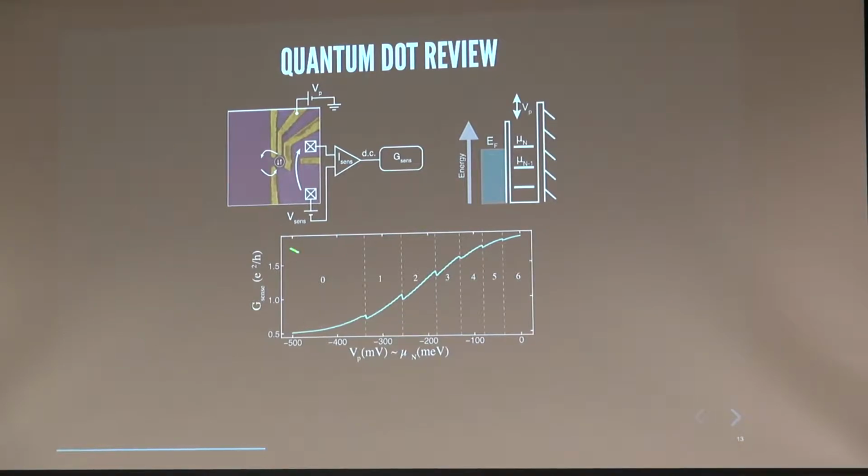So here we have a big blank region. There's no electrons in this dot. No matter how negative we go, we can't go less than 0 electrons in here. But then when we get here to about minus 350, the first electron jumps in here from the reservoir. These arrows are showing you the arrival or departure of an electron. Okay, so the electrons jump in one at a time. And so here you see the first electron, second, third, fourth, fifth.